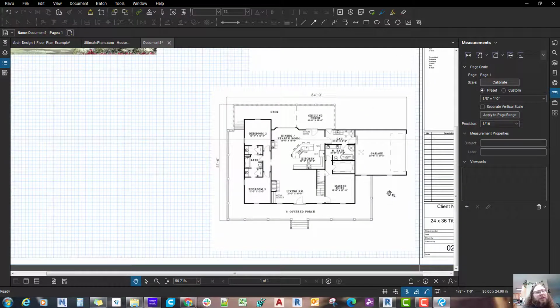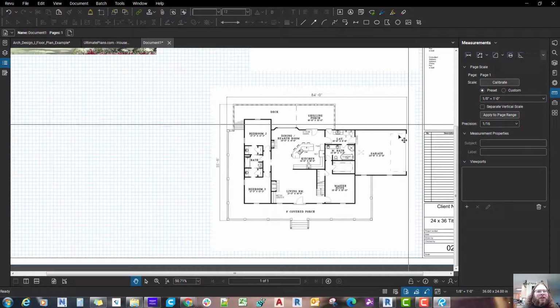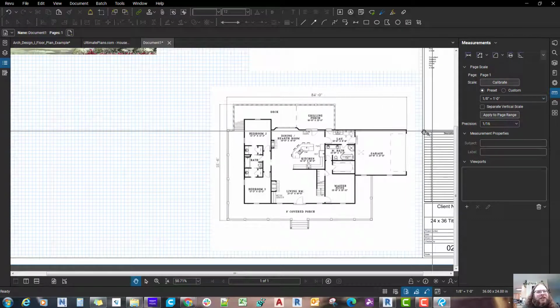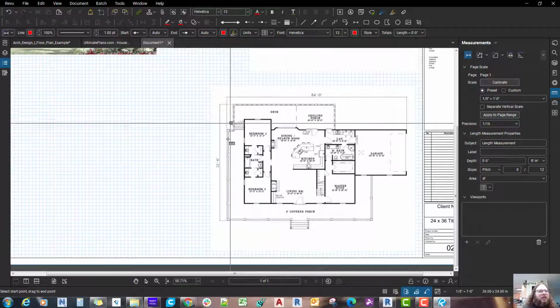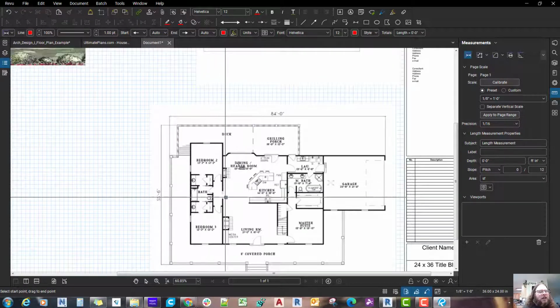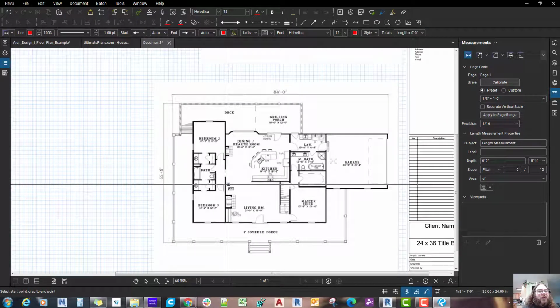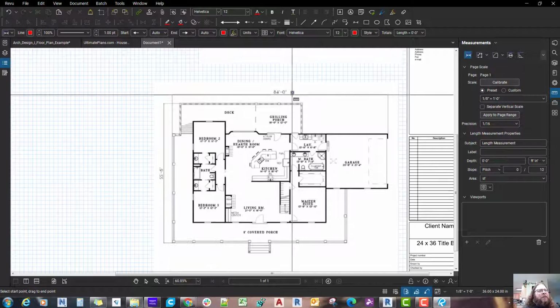Typically contractors are going to want to work with 1/4 inch or 16th at the max, because when you're throwing a tape out there, you need to have some tolerance built in, and really precise 32nd dimensions just aren't practical for the guys in the field.